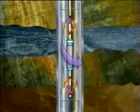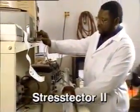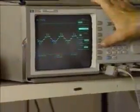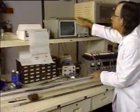The ability to read left-hand torque is essential in certain fishing situations. Another advantage of the Stress Tector design is its durability. It can be run in combination with string shot explosives, which reduces the time involved in freeing the stuck string. A new version, the Stress Tector 2, is being introduced for slim hole, coiled tubing, and high temperature situations. The smallest size Stress Tector 2, at 5/8 inch diameter, has been developed to handle pressures up to 20,000 psi and over 400 degrees Fahrenheit.